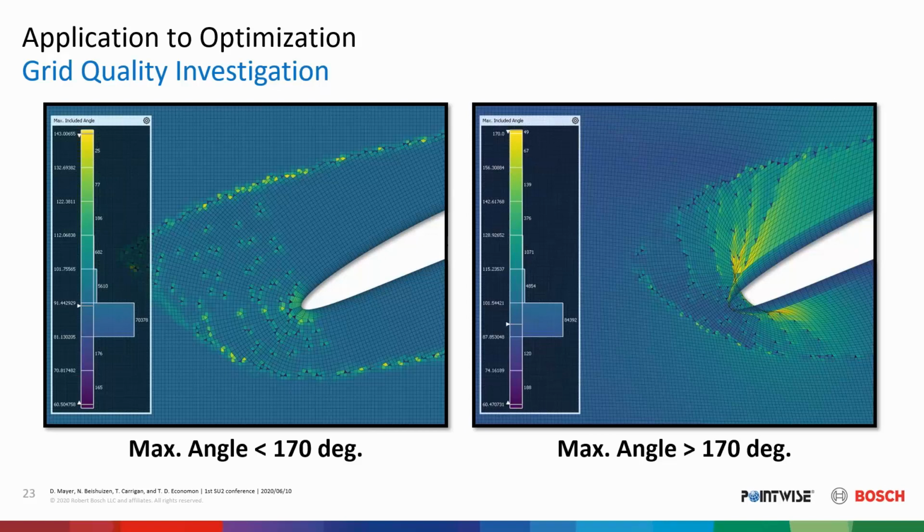And this is a little bit different approach than the first cycle that Daniel showed you, where you would deform a mesh and run a simulation. And if the simulation, say, diverged, that's a case where you want to further investigate and see if it's a problem with the mesh and then consider remeshing.